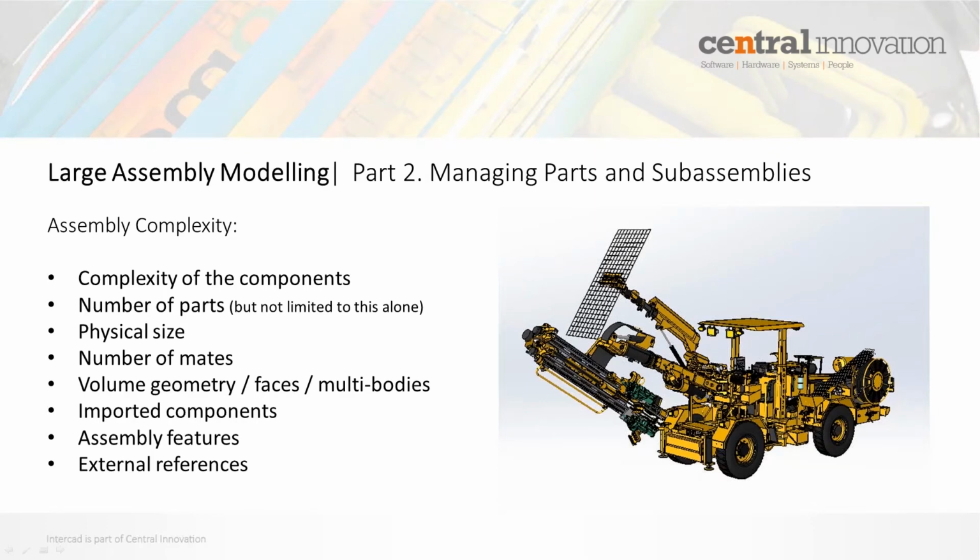They're probably a good thing to keep an eye on. You need to know where your references are coming from and where they're going to, so that they don't end up in conflict or creating circular references. I guess all of these factors can contribute to performance issues when working with large assemblies. One of the biggest issues though in working with large assemblies is getting them loaded in the first place. So let's have a look at that.